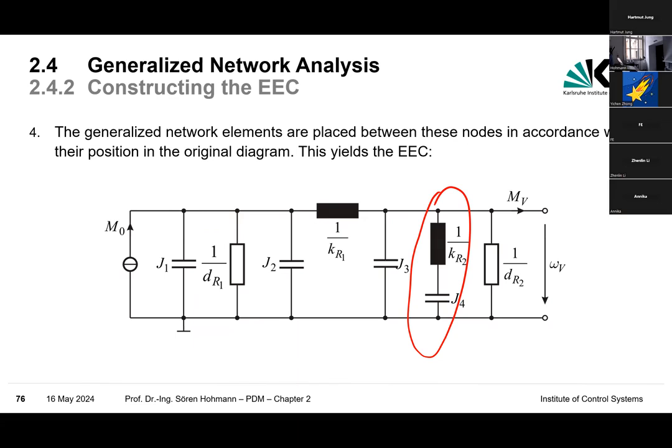That's important. It becomes really complex and difficult if you try to position a mechanical capacitor somewhere in between two nodes where one is not the ground, because then you have to define the different relations between the different nodes' effort variables. This makes it very, very complex.